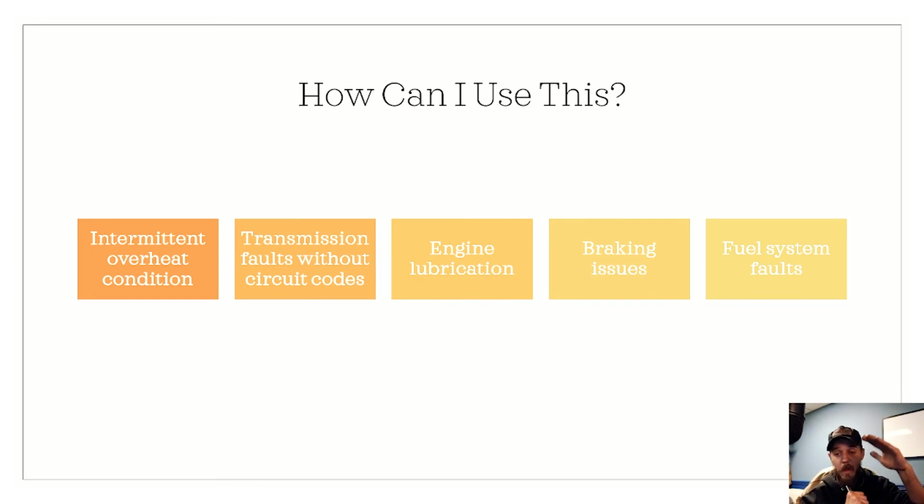magnification, uses the fact that fluids are virtually incompressible, and attempts to compress them, which exerts a larger force, multiplies the pressure. So you go from a base engine oil pressure of 40, 50, 60 psi to 1800 psi, right? That high pressure oil is then used to fire another plunger working on the hydraulic principle.